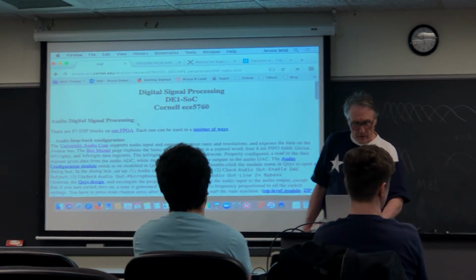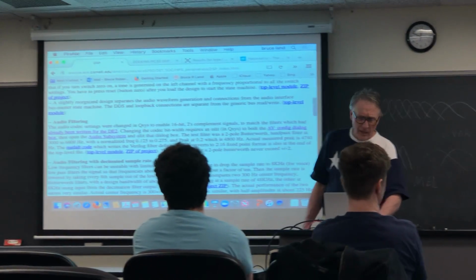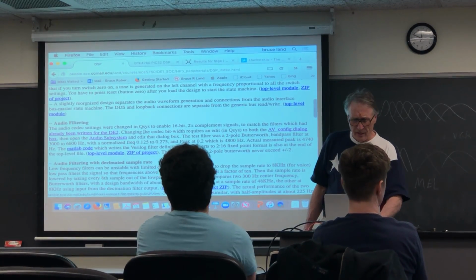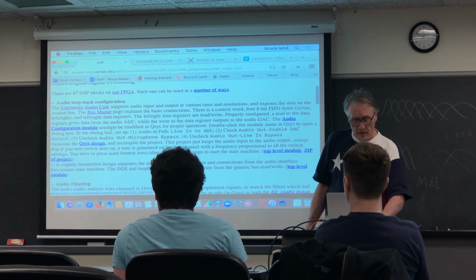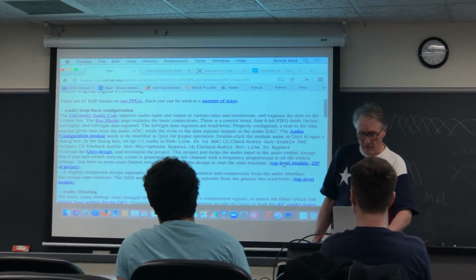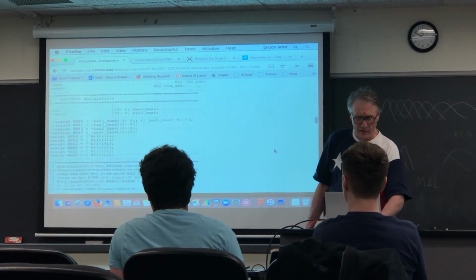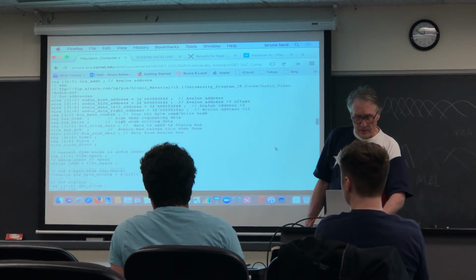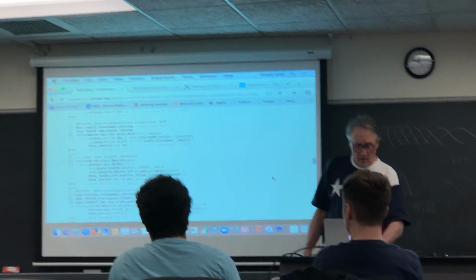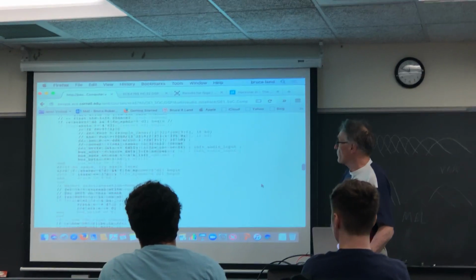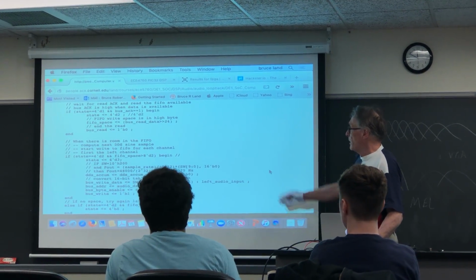So now if we go back and look at what one of these filters looks like, I've written all these for the DE2, and the code is exactly the same because it's just Verilog. The stuff that has to be hacked is the audio codec, which is worked out here. But the basic thing is there's a bus master for reading and writing from the FIFO.